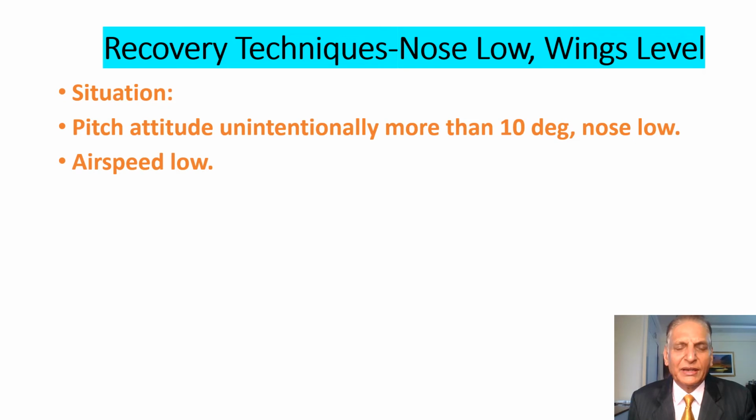Now we shall discuss recovery techniques, nose low, wings level. The situation, the pitch attitude unintentionally more than 10-degree nose low, airspeed low.